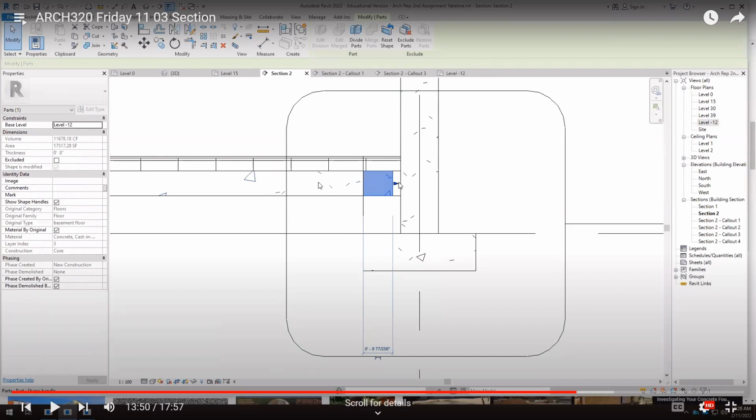This is the concrete cast in place, but the concrete slab doesn't get to the concrete wall because we need a joint, because if this slab expands, it may affect that wall. So we need an elastic joint here made of rubber or another tiny piece of thermal insulation, so that if this slab expands in this direction, it doesn't affect the structural wall here. Okay, so that's why I have dragged all the layers up to this wall. At the concrete slab, there will be a joint here, and we will define that material in the detail.